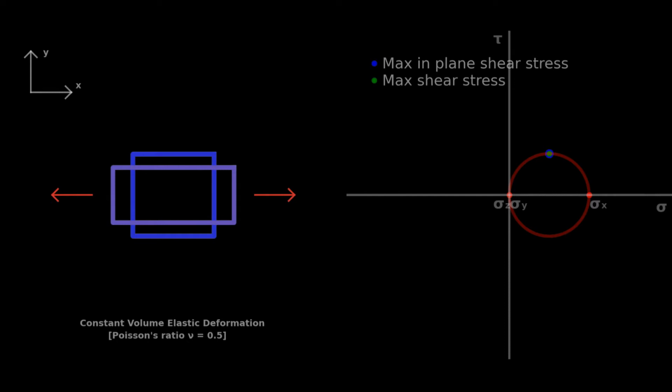The idea of the Mohr circle is that the element is experiencing a different combination of stresses at different angles. Therefore, the points defining the Mohr circle can rotate together around the circle to determine the stress state of the element at that particular angle. Notice that if we rotate the element by 90 degrees, the x and y stresses would switch. If we look at the Mohr circle, we need to rotate 180 degrees to switch the stresses. Therefore, we expect that a rotation in the element corresponds to a rotation of twice that on the Mohr circle. This will become more clear later.